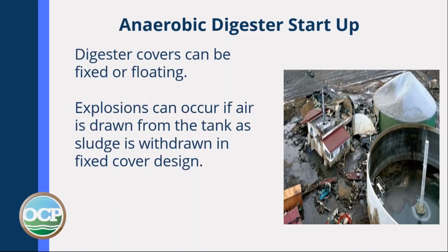For digester startup, like we said, covers can be fixed or floating. If you've got a floating lid, a floating cover, you need to make sure as you're drawing air or you're drawing sludge out of the top that you don't let air get in your reactor with either cover design, either fixed or floating.